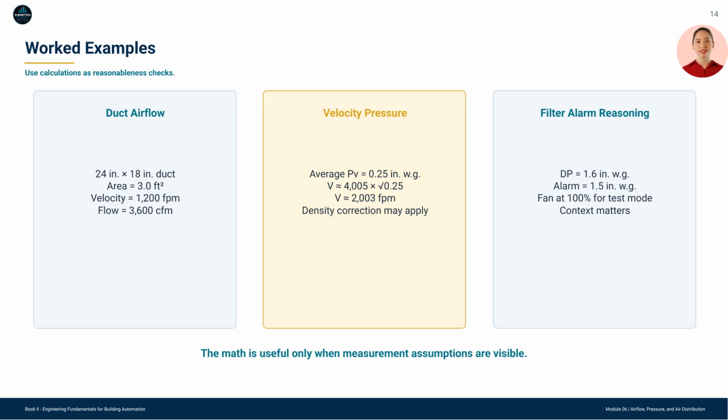Do not treat these calculations as paperwork. Use them as professional questions. Does the result match the equipment size? Does the flow match the balancing report? Does the pressure match the sensor range? Are the units correct? The math is valuable because it forces the data to prove itself.